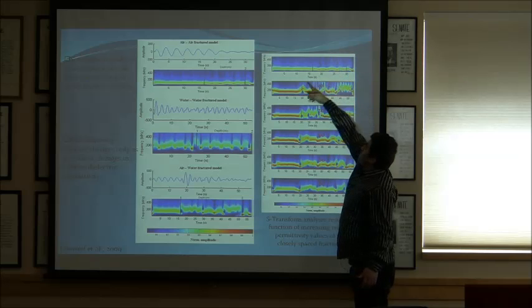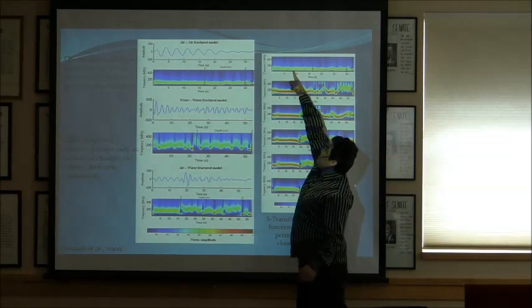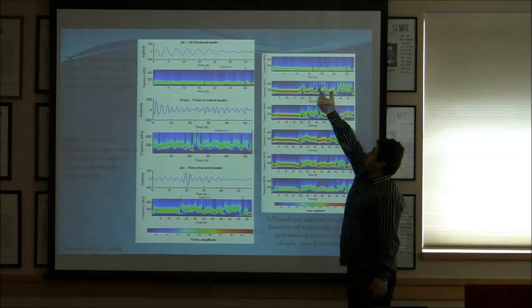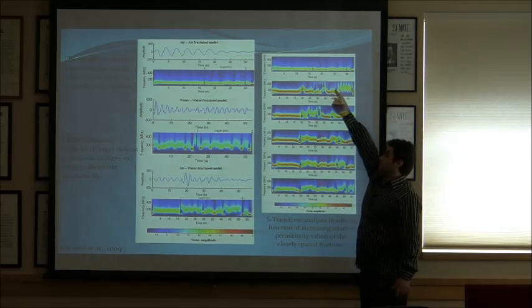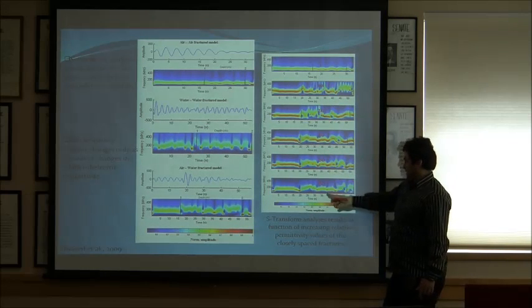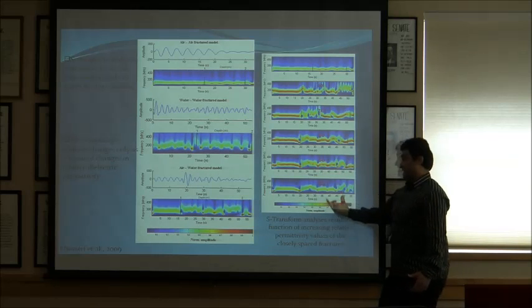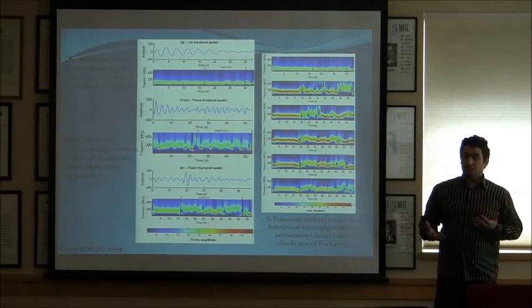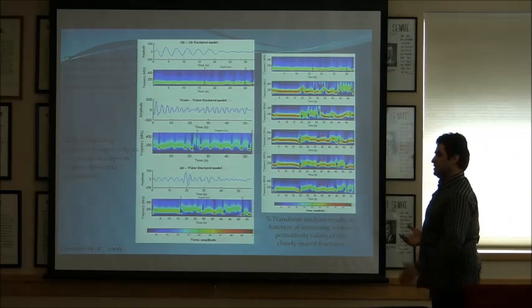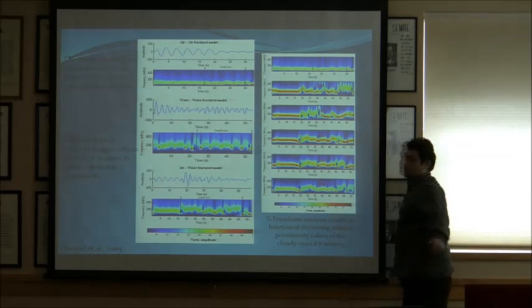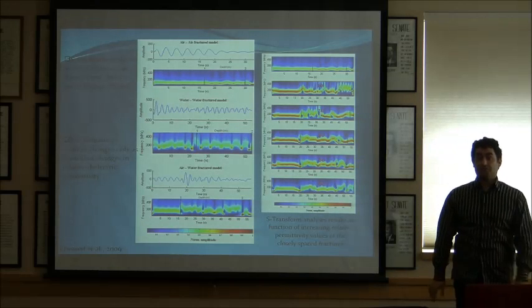Here is the original case where there is no change in dielectric permittivity. Here, you have a change of 10. For the closely spaced set, 20, 40, 60, 80. As you increase the water content, you have an enhanced shift. So that tells us there is a dependence between the dielectric permittivity change and the frequency shift.